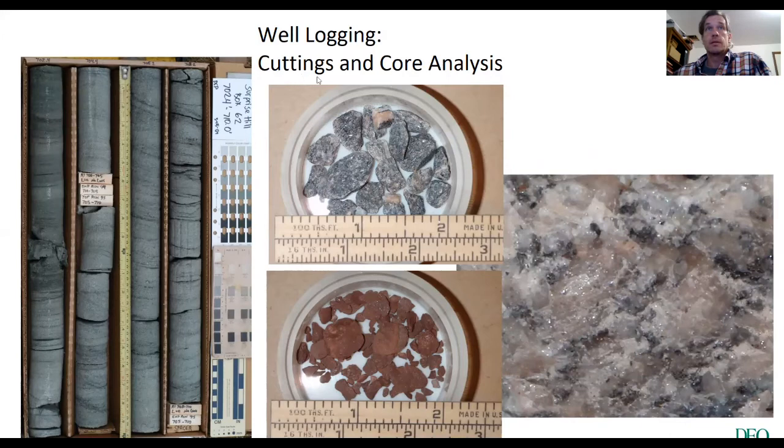Well cuttings, core analysis, looking at outcrop may help you define or establish features like no flow boundaries or recharge boundaries just by looking at the lithology and the geology of the system. And you've seen this core from the coastal plain talk, this is Potomac Aquifer sands. I forgot to mention this, but this is all core material. It's been pulled out in a tube and extracted. And that's how you learn about the geology in a lot of the coastal plain.